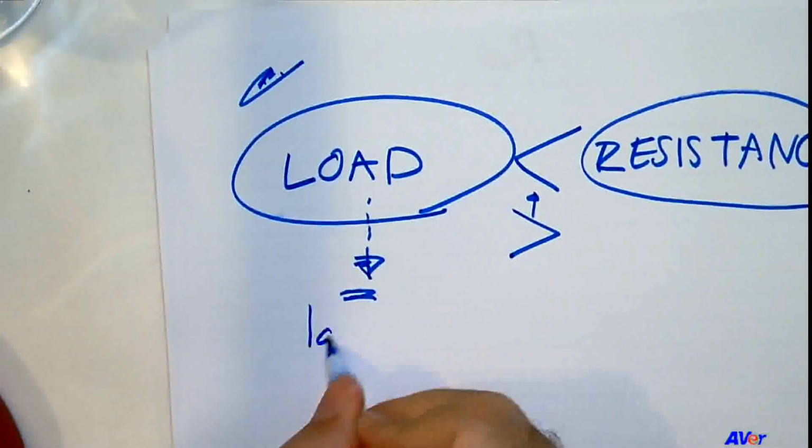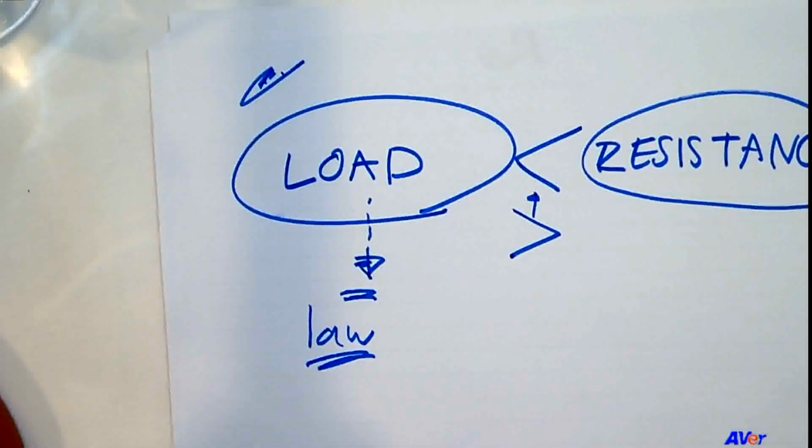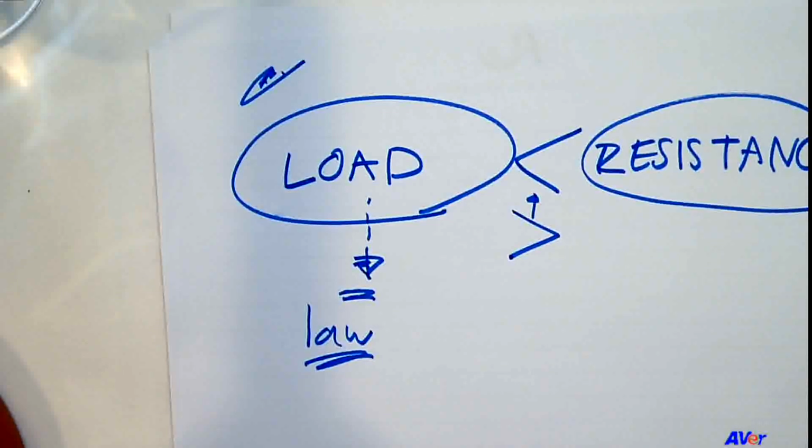But as an engineer, the law is just some sort of prescription that you need to follow as a minimum requirement. Okay? So that means if the law says you have a building and it needs to be able to withstand the live load equal to 200 kilogram per square meter, if it is an apartment, that is the minimum requirement. If you as an engineer feel that 200 kilogram per square meter, not centimeter, sorry, is not enough, it is not safe for this building because you know that according to whatever the events in the future, 200 may be too small.